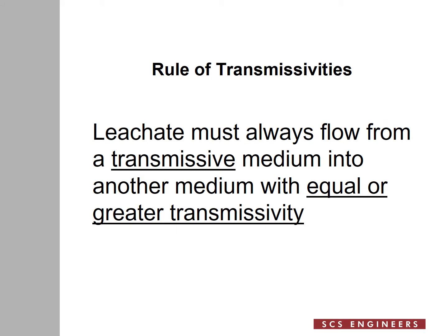Before we continue with the subject of clogging, I would like to present to you a simple rule that I refer to as a rule of transmissivities. Leachate must always flow from a transmissive medium into another medium with equal or greater transmissivity.